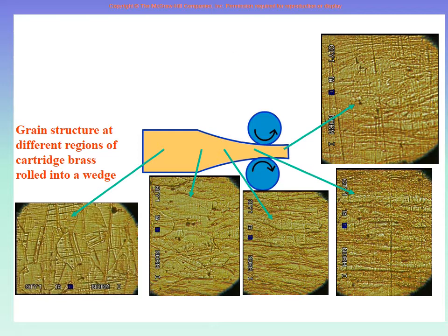So this is what we told you, that with plastic deformation, the shape and size of the grains changes, especially in an operation like rolling, because in rolling all the grains are elongated, so the length of the grains becomes larger. In some other plastic deformation operation, the shape may change, but maybe not the length, maybe some other shape change happens.